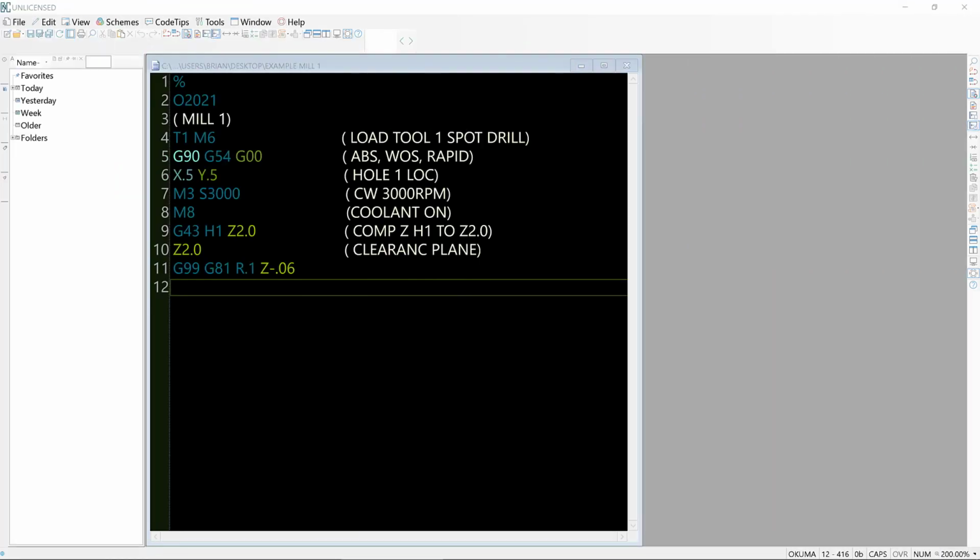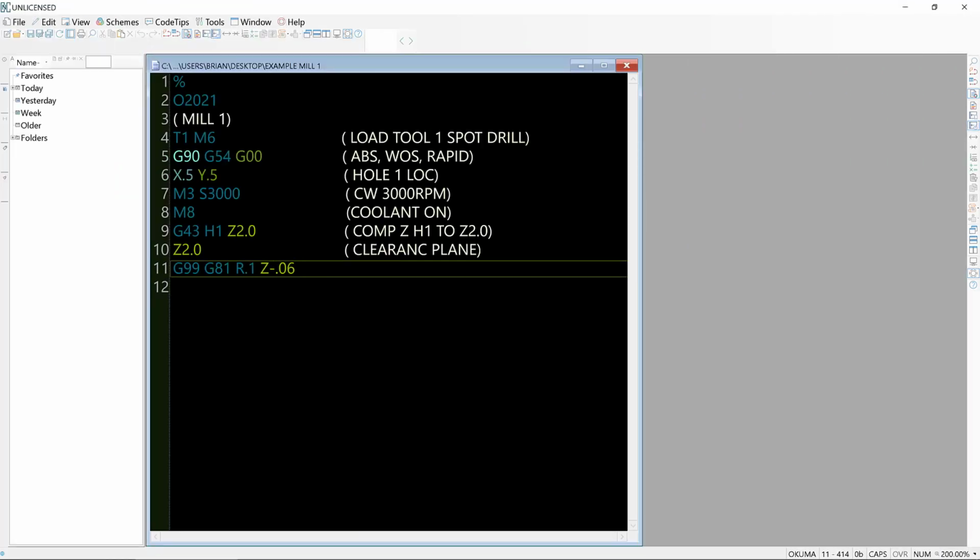Alright, so let's continue. Let's get our feed rate ready for this drill. We're going to use a 3 thou inch per rev spec for this drill, because drills are usually called out in inches per revolution. Now, we could change our codes and interpret this in IPR, but that's kind of abnormal. So we have to convert our 3 thou IPR feed rate into inches per minute, which is standard on the milling machine.